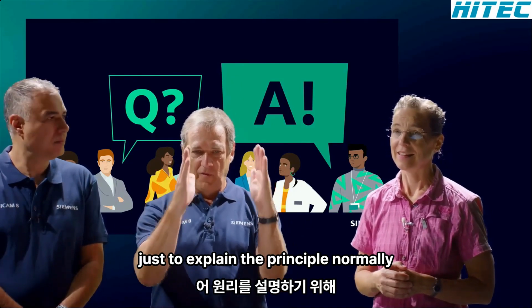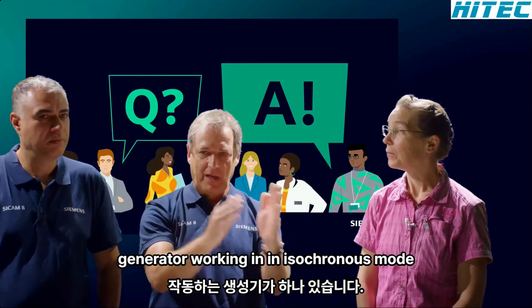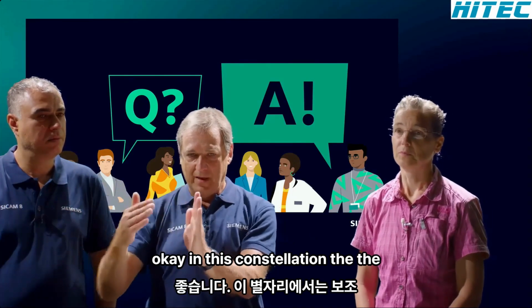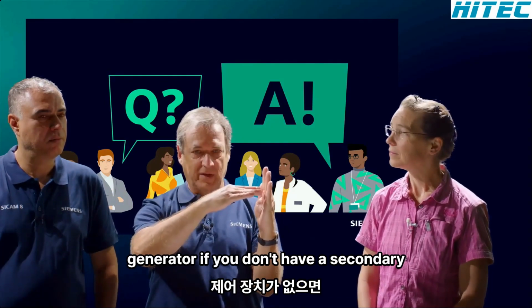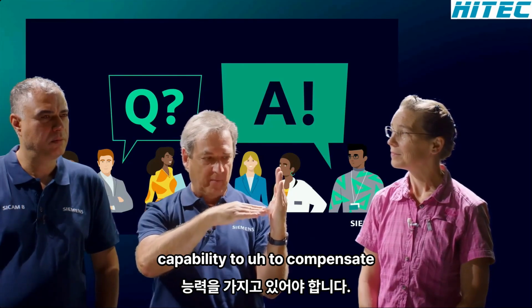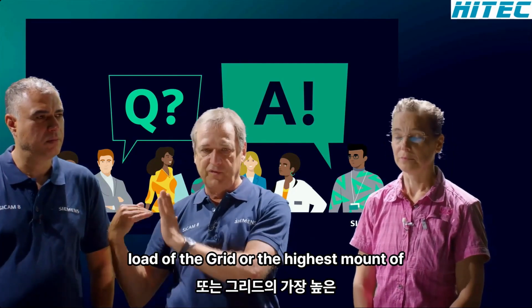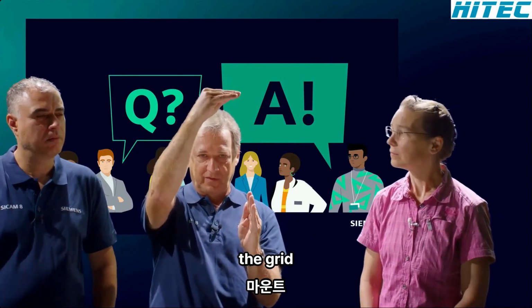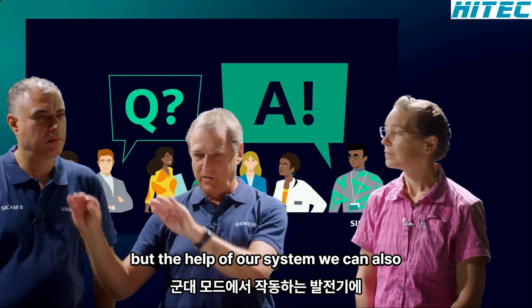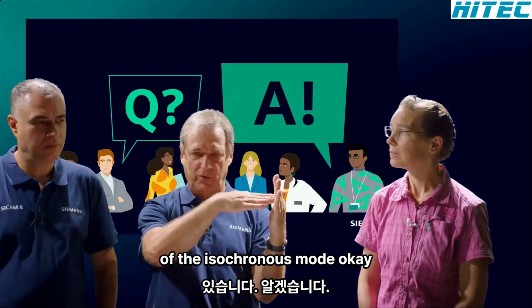Just to explain the principle, normally you have one generator which works. If it is a smaller constellation, you have one generator working in isochronous mode. And then you have other generators helping this generator, supporting it, working in droop mode. In this constellation, if you don't have a secondary control, the first generator working in isochronous mode must have the capability to compensate the smallest load or the highest amount of the grid. By the help of our system, we can also influence the generators working in droop mode so that the first generator always remains in the middle of the isochronous mode.